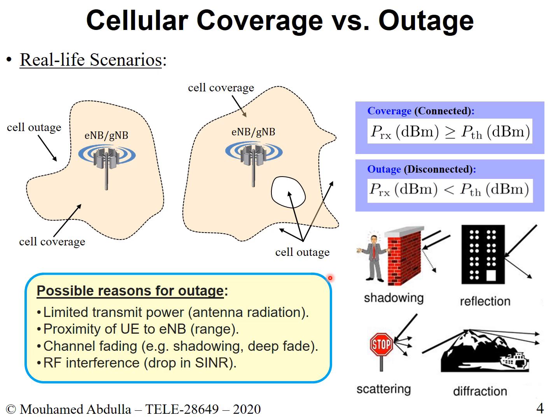Another reason for getting outage is perhaps radio frequency interference, or RFI. Now, interference, we talked about it before, and we said interference is caused by other devices that operate in nearby operating frequencies or bands, and that causes interference. Or it could be similar devices that overlap with the channel.